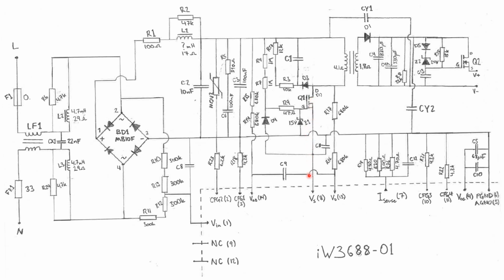I would check if the MOSFET is shorted, if I can measure the body diode with a diode measurement, and I would measure the resistance over the shunt resistors here, make sure I have the right resistance, none of those have burned. And following the path out here, I would also measure L3 for continuity to the common mode choke and check that my fusible resistor here has 33 ohms.